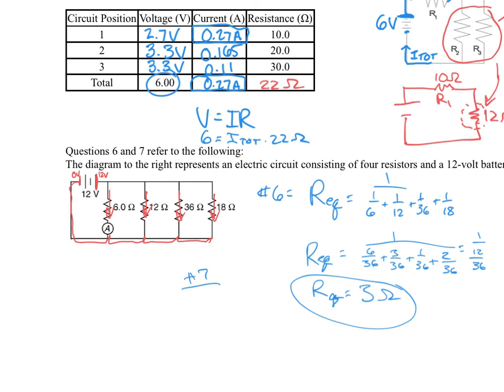So I have 12 volts. I'm going to drop 12 volts regardless. So I know that there's 12 volts of drop across this branch. Let me pick a different color here just to show this easier. So I got 12 volts of drop across this, and I got 6 ohms of resistance, so that makes the math pretty easy. V equals IR. The 12 divided by 6 is going to give you a current of 2 amps flowing down that channel.